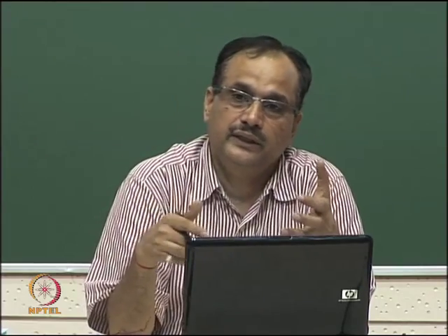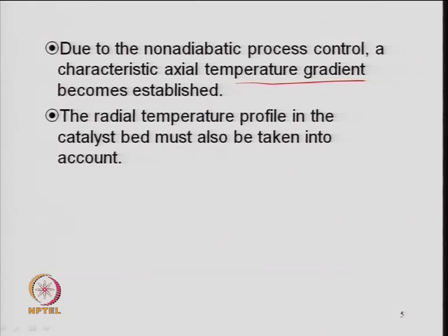In the adiabatic process, heat is neither added nor removed from the system. In non adiabatic, you are controlling the heat, either by removing it or by adding it into the system. There will be a temperature gradient in this non adiabatic process. The temperature is increasing down the length, suppose the reaction is exothermic. That gradient will come, and that will affect the performance.